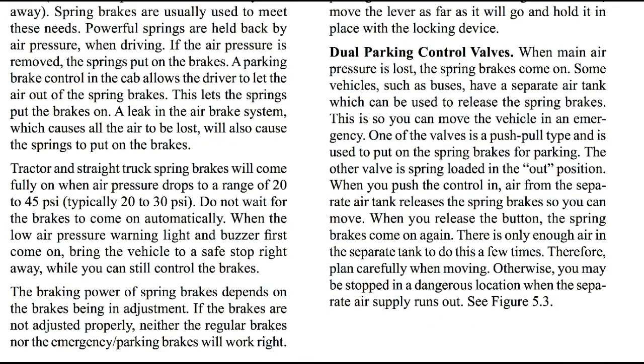Dual parking control valves. When main air pressure is lost, the spring brakes come on. Some vehicles, such as buses, have a separate air tank, which can be used to release the spring brakes. This is so you can move the vehicle in an emergency. One of the valves is a push-pull type and is used to put on the spring brakes for parking.